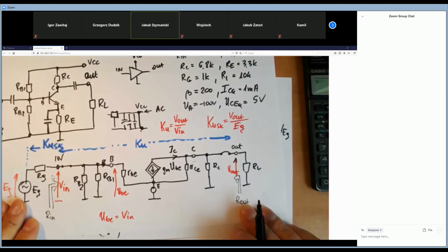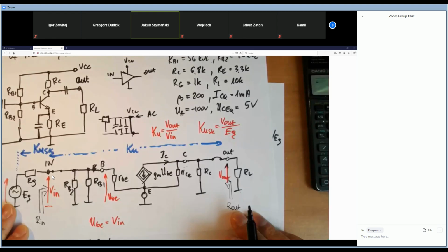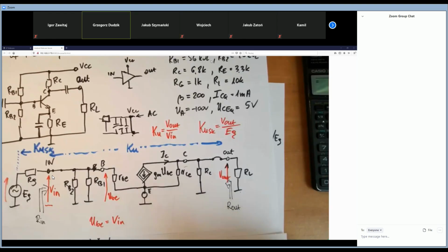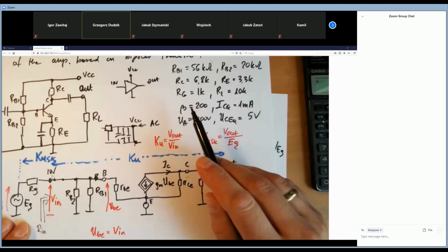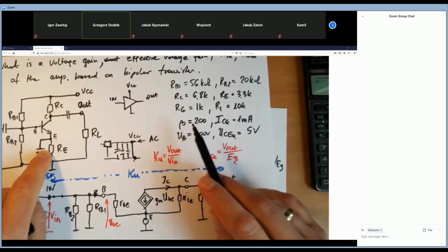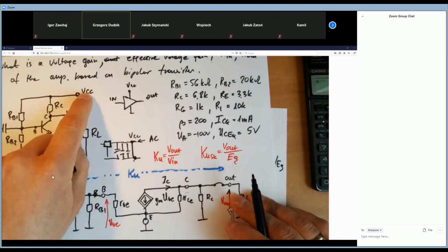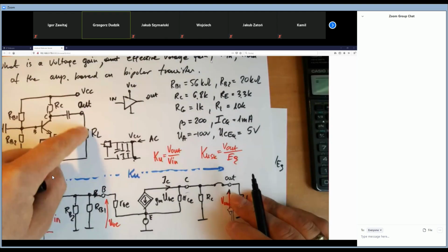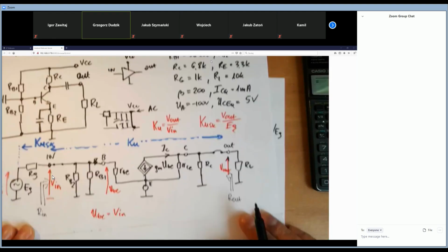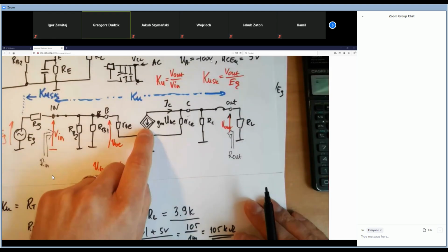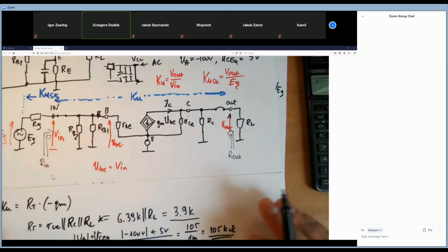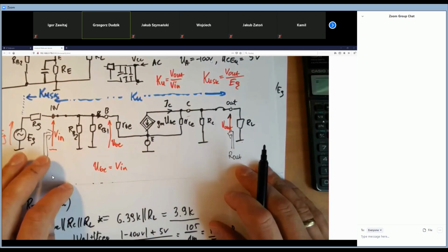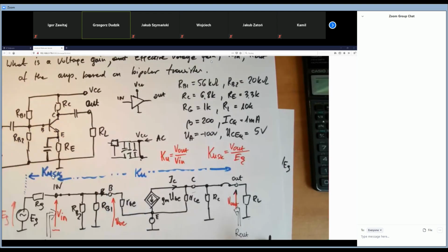If we supply this voltage and choose the correct transistor? Yes, Jakub, you are right, it is possible. However, we have to supply our circuit not by 10 volts for the VCC, because if you have the VCC equal 10 volts, it is not possible to get a higher output signal than 10 volts. But we have to choose the correct transistor, which will not be broken by so huge voltages. So you have to remember the limitation of the output signal for amplifiers: it is the VCC.